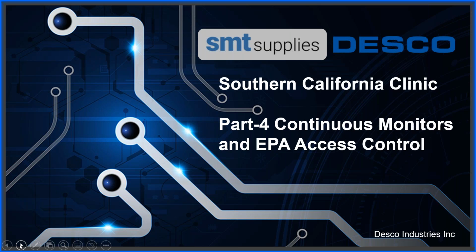As far as the EPA access goes, I'm sure most of you know, EPA stands for electrostatic protected area. Now in the standard, an electrostatic protected area is required to be defined. What that means is you should have in writing in your ESD plan where those areas are, a lab, the entire building, a room, wherever that is. Typically you would identify those areas with some kind of signage, maybe aisle marking tape, caution tape, signs on doors, signs on benches, to make sure not only the employees know they're in an EPA, but visitors as well. So I'm not going to spend a lot of time on that.